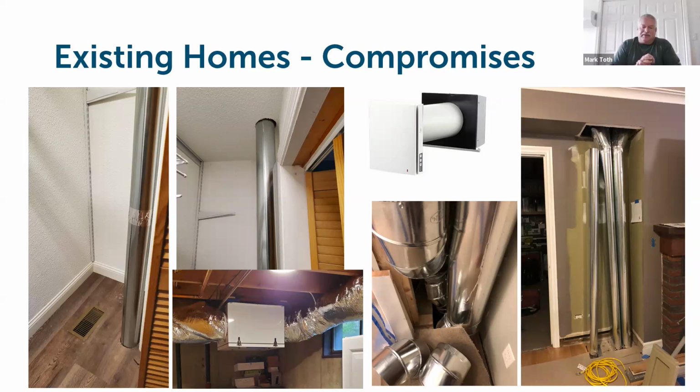We've got to put a ventilator in. So we put it in the basement in the mechanical room. As you can see on the left, that's up through a first floor closet going up to the master bedroom upstairs. This terminates under the bed in the master bedroom. The outgoing air we took out of the finished basement just outside the mechanical room wall.